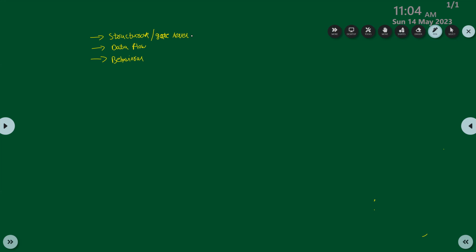Before explaining these 3 types of data flows, first you have to understand module definition and module instantiation. Module definition means you start with the keyword module and the name of the module, and then optionally you can use brackets, if you want to declare variables there itself. Otherwise, you can declare them directly inside and end with endmodule.